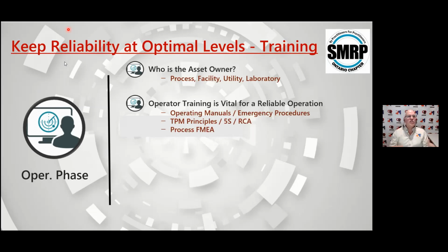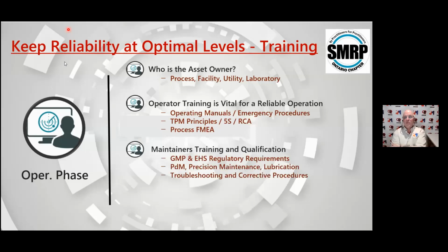Sometimes when I do RCM analysis or reliability analysis in the pharma industry, we ask to see if there is some previous RCM analysis or RCA done. You don't find it too often, but you do find process FMEAs. And in the process FMEA is where you understand the risks associated with the product quality, right? So let's discuss the process FMEAs with operating people so they can understand the risk associated with operating those assets.